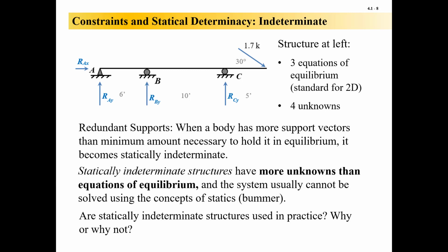Are statically indeterminate structures used in practice? What do you think? All the time. There are probably more statically indeterminate structures in real life than there are statically determinate structures in real life. Your house, the walls in your house have studs every 16 inches. You cannot determine what the axial compression is in each one of those because it is a statically indeterminate system. We have way too many studs in there. Why do we do that? We do it because the redundancy is good, right?